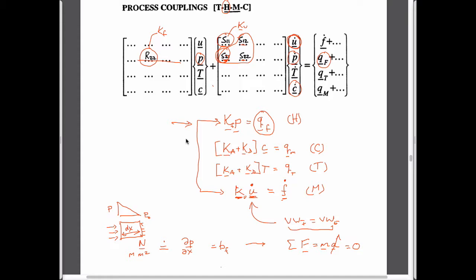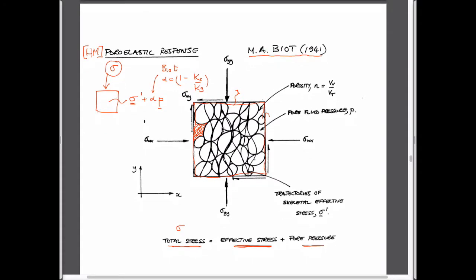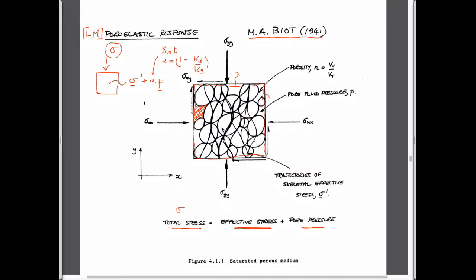So the two systems are linked, if you like, in a physical way, by a body force which results from the fluid pressures in the mechanical expression, and mass flux by squeezing fluid out of a sponge as you deform a sponge and squeezing it out of the control volume in the fluid flow equations. So that's kind of where we'll end up. It's always useful to keep the physical interpretation of this in your mind.